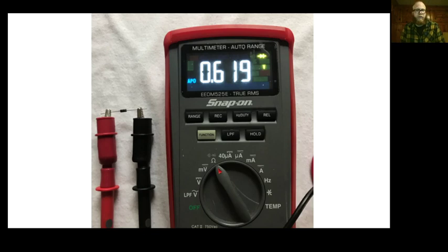Here is me with my meter. And this is in the lab. You'll see an image of this. I have my meter on the diode check function, because you can see an image of a diode here. And it's nice that they display the volts after this. I think that's important, because what this is telling me is not that I have 0.6 of an ohm of resistance. It's saying 0.6 of a volt is what you need to get this diode to forward bias and flow. If I flip it around, it says OL, and you'll see this when you do the lab,